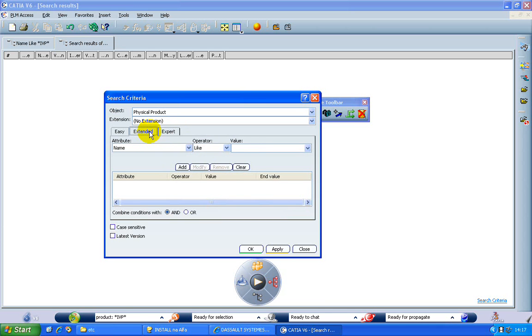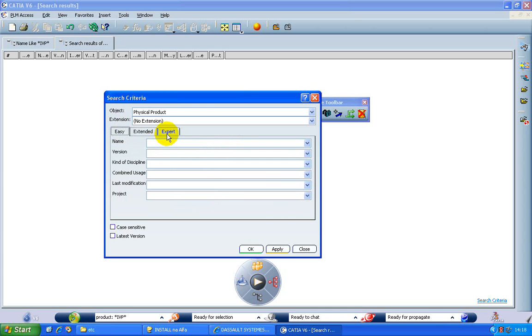I can perform different lifecycle operations on my part. It means I can lock and unlock the data. What is important when I use lock or unlock is that I use it in case of concurrent engineering, it's very important to avoid that someone else is performing a modification on the same part at the same time. Okay? If you are alone in the company, working alone on the computer on the database, so that you are sure that no one else can perform the modification, then it's useless to use lock or unlock status.